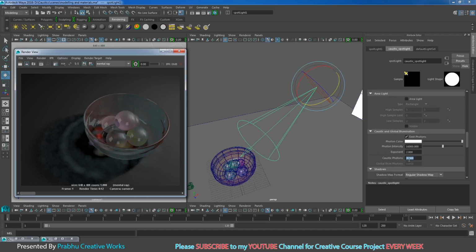So I will increase much more. I will give 50,000 photons. I will keep this image and click render again. Now see it has a little more accuracy for our caustic patterns. It also increases our render time. See, it goes from 12 seconds to 13 seconds. Remember, when you increase caustic photons, your render time will be much higher.